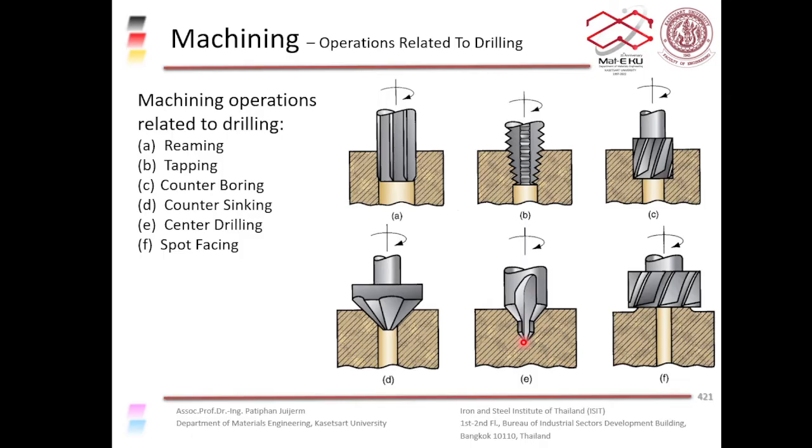And then because you have the center of the hole marked by the centering process, you can use a bigger drill bit to actually drill the hole, and you can be sure that the center is exactly the distance that you want because you already measured the distance to the center.